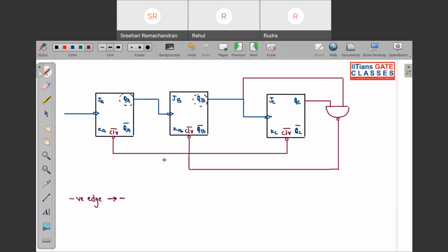And the clock is being supplied from the normal output. So that means what? Normal output means plus. So this is different in sign. That means this is an up counter. This is your up counter.